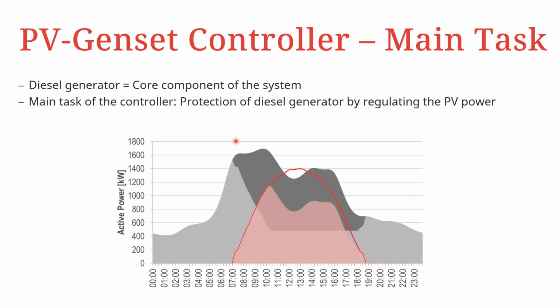So let's now have an overview of how this system can be designed. First off, as mentioned, we need to know the minimum genset loading. Basically, the minimum genset loading falls between 25 to 30%. For those that don't know, the minimum genset loading point is a point that the loading of the genset must not go below. Okay, so this is usually 25 to 30%. If you're loading a genset, it mustn't be below 25 to 30% of the genset capacity.